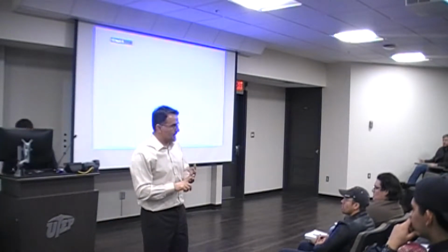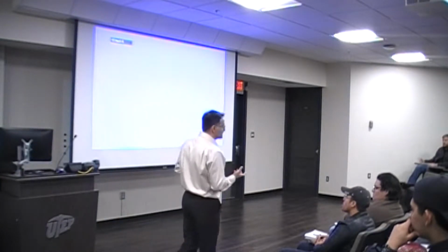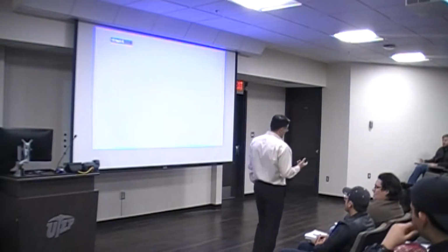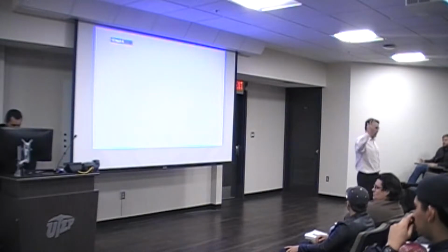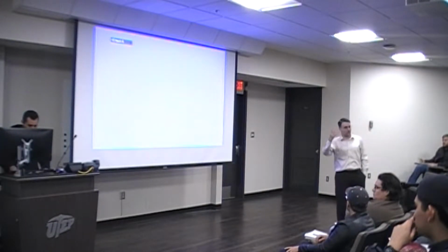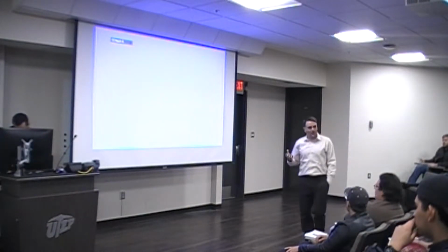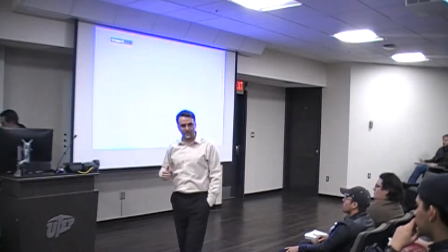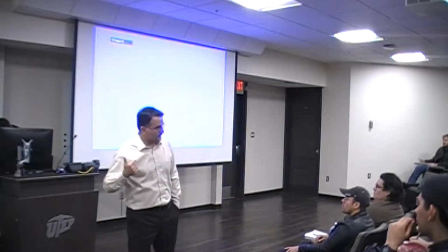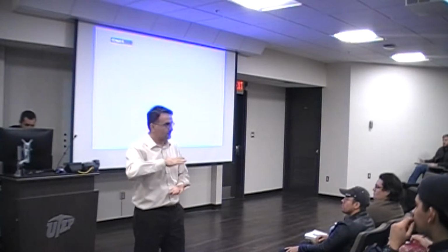The volume goes down. Can you tell me what happens to the density of the soil? The density of the soil will increase, right? So the density is simply weight or mass divided by the volume, right? The mass or weight stays the same, the volume goes down, the density will be higher, right? So what happened? The soil densified underneath the pressure.